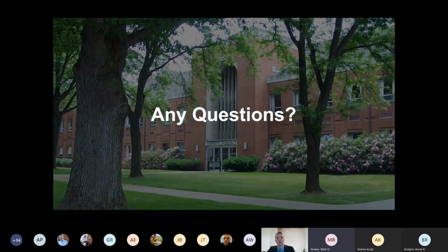Again, I guess I can answer that. So the only restrictions, we didn't have a set ratio. We just looked at ceiling height and what our clearance was above the ceiling. In the first floor, we just made things as shallow as possible and as wide as possible because we don't have as much clearance there. In the second floor, we just kept everything at least 2 times as wide as it is tall. But most of our requirements were just making sure they fit in the ceiling space.